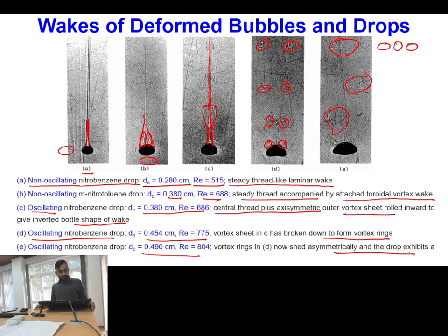Okay, so in the majority of these non-oscillating regimes you will have almost smooth and steady motion of the particle. Okay, on the contrary, when you have the shedding of the vortex and shape oscillations in the fluid particle, then your motion will not be straight. Either you will have spiral motion, or you will have rocking like reciprocating motion, or planar zigzag motion. Okay.